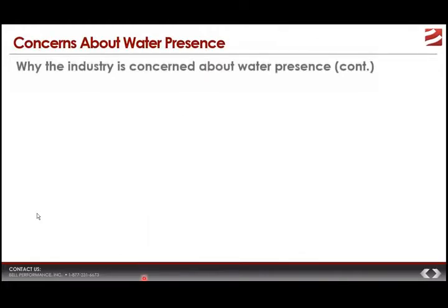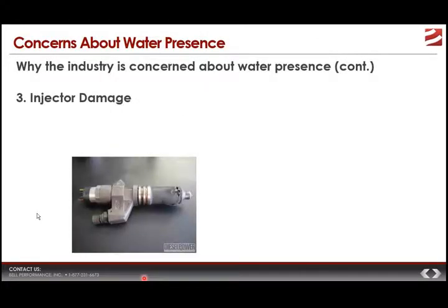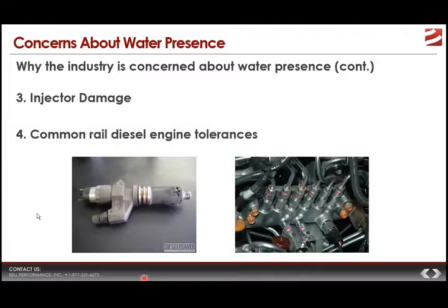The third reason is injector damage. It's been well known for a number of years that if you get a little bit of water in the tip of a hot injector, it turns to steam, blows the injector tip out, and shuts the engine down. And then there are the newer common rail engines today, which use a common rail in order to help control the injection of the fuel, with the fuel injectors.